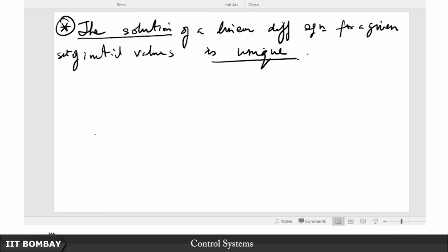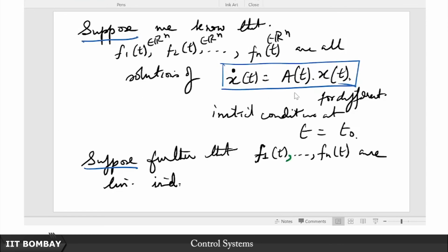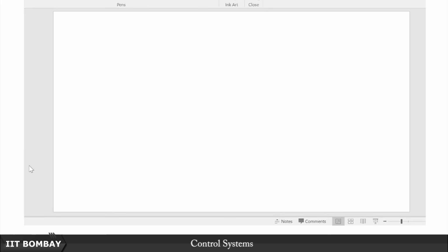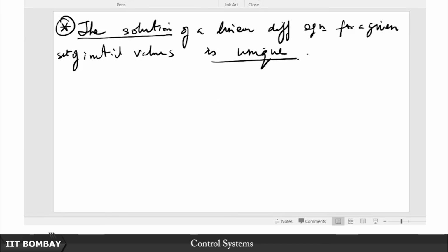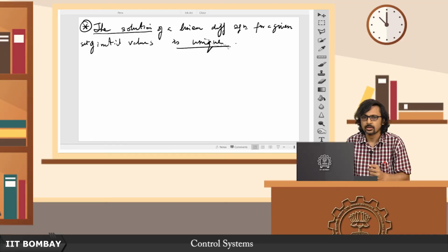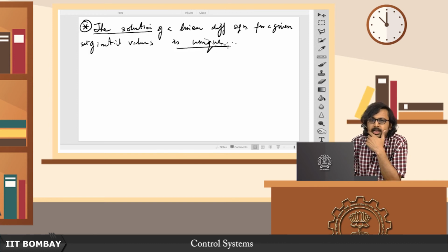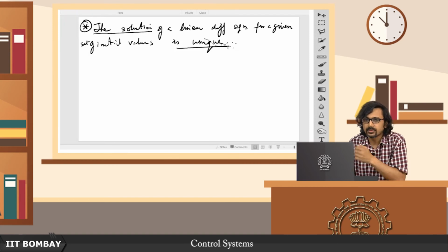So after all, this state space representation is coming from some ordinary differential equation with non-constant coefficients, where the coefficients themselves are functions of time. Essentially, like in the time invariant case, this is the representation of an nth degree differential equation as n first degree differential equations. So there is no other difference between this and the linear time invariant system, other than the fact that the coefficients here are allowed to be functions of time rather than just constants. This is what we shall assume; we will not prove it, we will take this to be given to us as true.